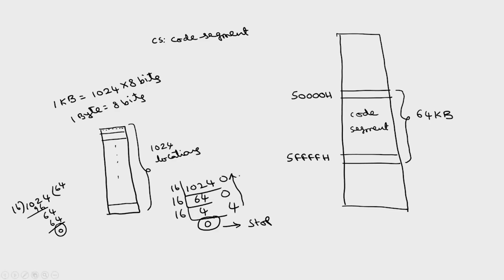So if I want to start with 0000H, because this is 400H, one less than this one is called 3FFH. For this 3FFFH, if I add 1, F is the maximum number, 15. In case of decimal, 9 is the maximum number. If I add 1, it becomes 10. So this F plus 1 becomes 10. Okay, if we start with 0, you have to take the value which is 1 less than this 400H. So this 0000H to 03FFH is called 1 kilobyte.